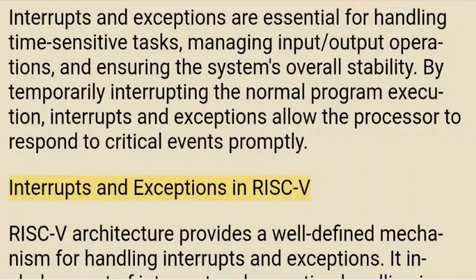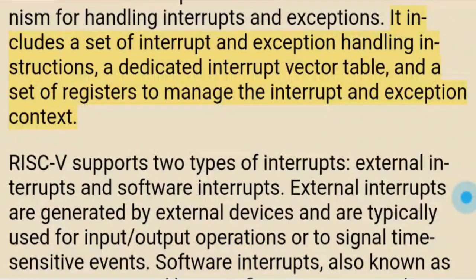Interrupts and exceptions in RISC-V. RISC-V architecture provides a well-defined mechanism for handling interrupts and exceptions. It includes a set of interrupt and exception handling instructions, a dedicated interrupt vector table, and a set of registers to manage the interrupt and exception context.